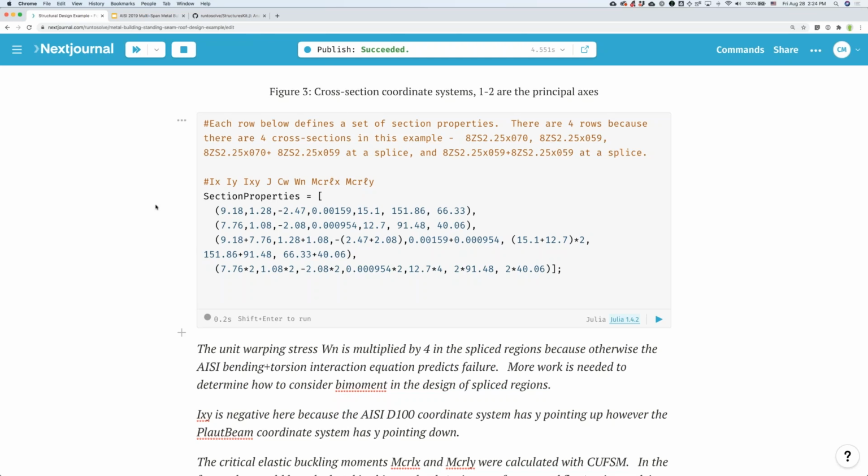especially considering torsion, because what we're seeing here is that torsion is limiting the capacity for uplift, and would be limiting for gravity too if I didn't tweak the numbers a little bit, and because we're using a first yield criterion for torsion. So torsion, interaction, and then a new set of tests, like multi-span tests, single span tests, or more tests that are well documented in terms of the behavior of the clip roof interface, the Purlin clip roof interface.